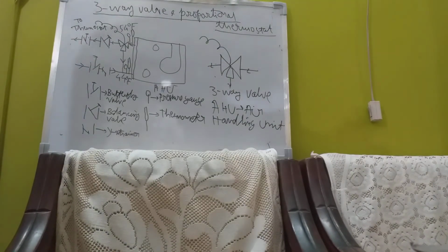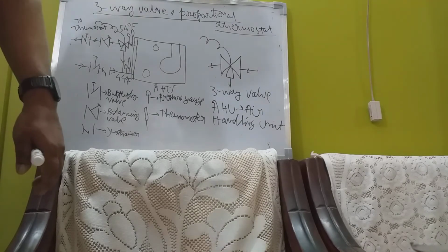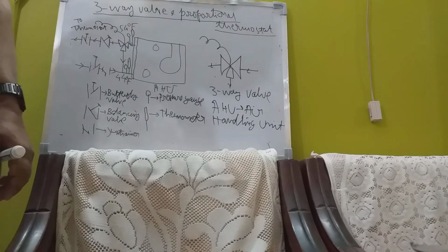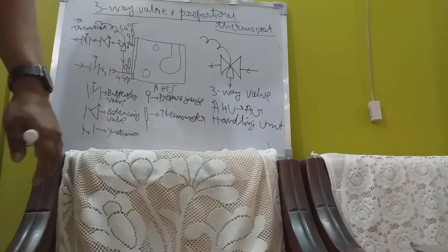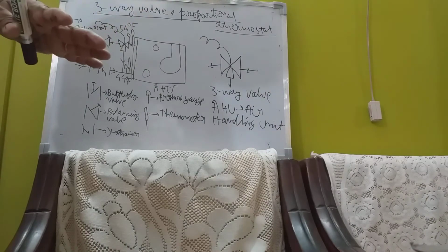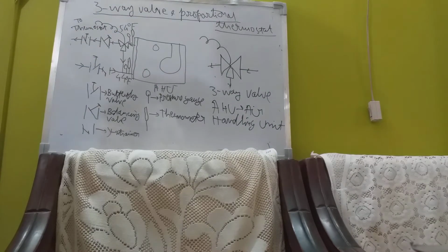There are 3 shopping malls, prominent shopping malls and other shopping malls. Every floor is supplied with a number of air handling units there. It's not only 1 air handling unit, because the floors are big enough and it cannot be taken by a single air handling unit. Not only that, there is another reason for putting 2-3 air handling units.